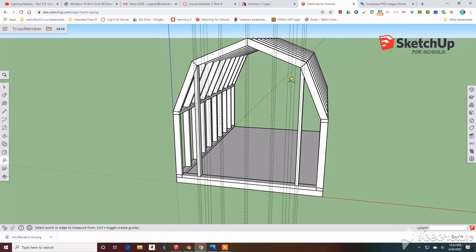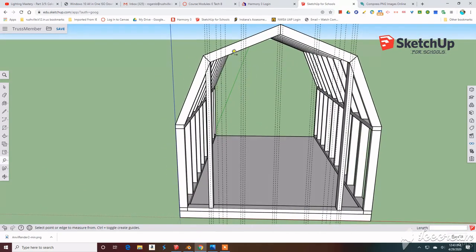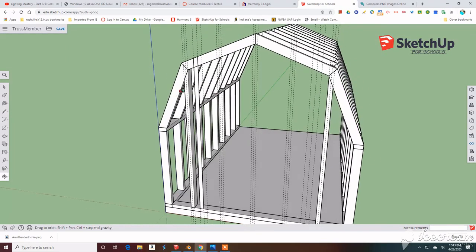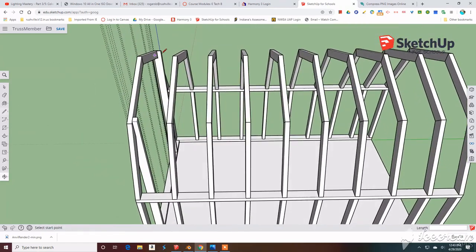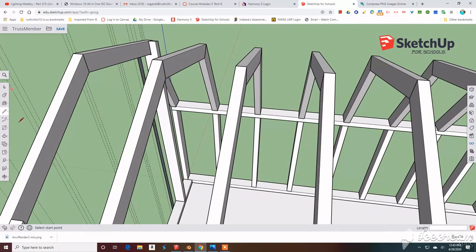Okay, now with that in position, we can go ahead and draw the door king stud. So pencil tool, using my intersection snaps. Remember, I need to draw 4 lines, and then close the polygon with that 4th line. And so now, since I have a 2-dimensional object, I can go ahead and use push-pull to extrude this back 4 inches. So 4 inches in the distance box.